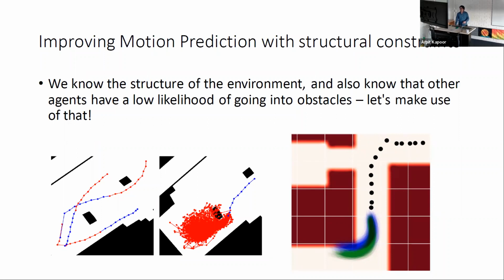The other thing that you'll realize is that it actually provides a very good initial solution for an optimization problem, right? It's quite close to being safe, but not exactly, right? And once we fix it up, it can look something like the green trajectory here, whereby it satisfies a chance constraint on the predicted distribution of trajectories being in collision.